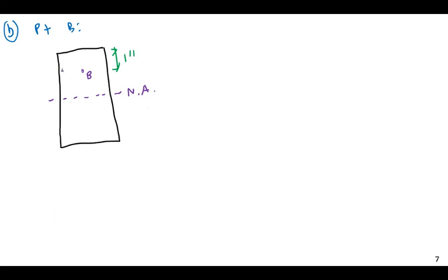Here. And so we're going to base our Q off of the outward area. Again, if I was asking for the stress at this location, I would actually base my Q off of the area downward. It is based off the minimum Q. In other words, look at this and say, which direction does the closest vertical surface lie, and calculate that. I have to be very careful with my language.